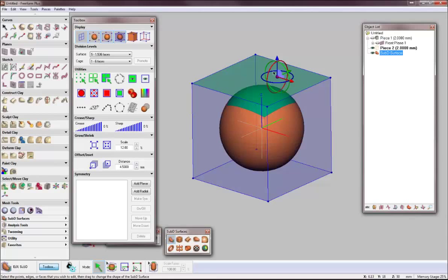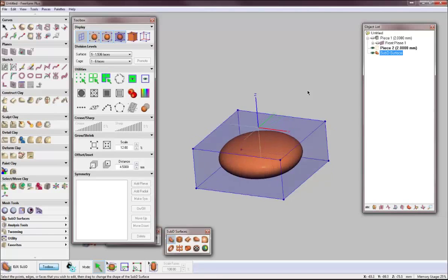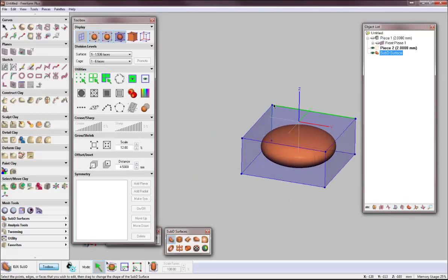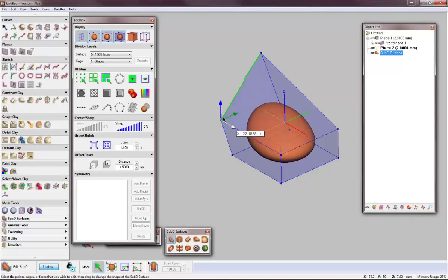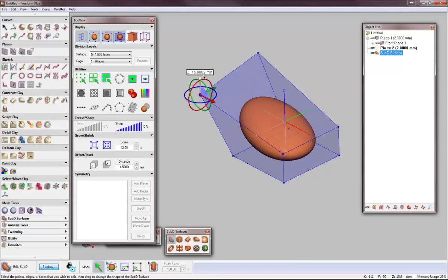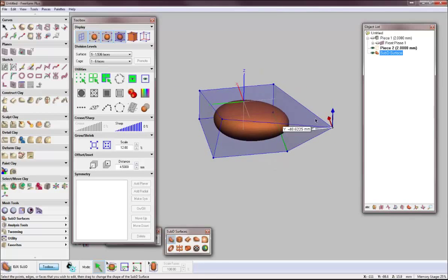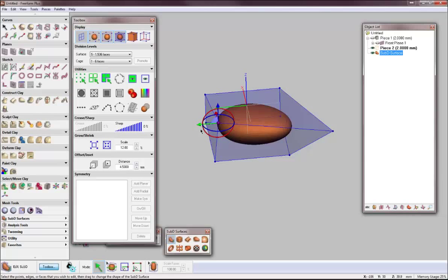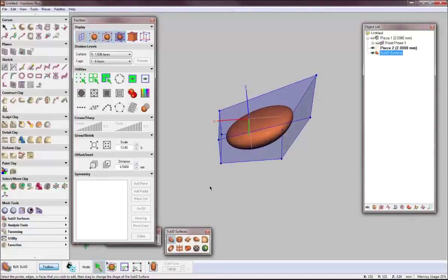If I just click on that face, you can see that I have that same gimbal and I can drag it up and down. And that was clicking on a face. I can also, of course, do the vertices. So I can drag those over and up. And for other tools out in this space, this is a familiar way of working with sub-Ds. So this will make people feel more at home in Freeform, just being able to use a mouse for the haptic modeling subdivision surfaces.